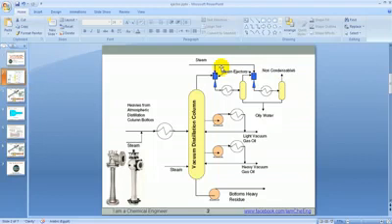As an addition to this system, to reduce the pressure even more and to efficiently get higher separation, you can use stripping steam. Stripping steam follows the exact same rule as the jet ejector. Stripping steam can reduce the partial pressure of the hydrocarbon entering here, which means reducing the partial pressure even more dramatically, bearing in mind that we are going to use a steam jet ejector in here.